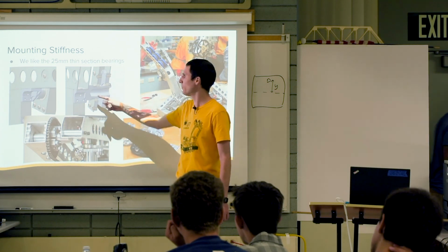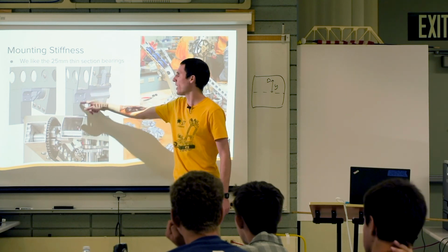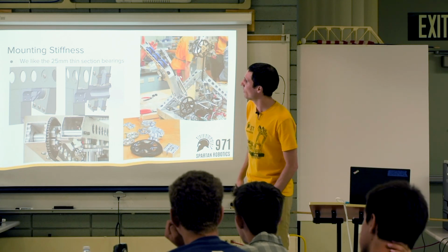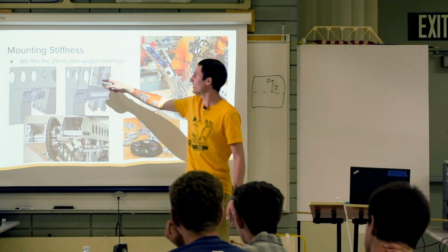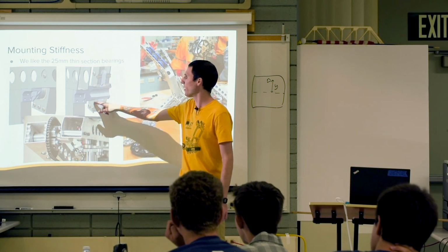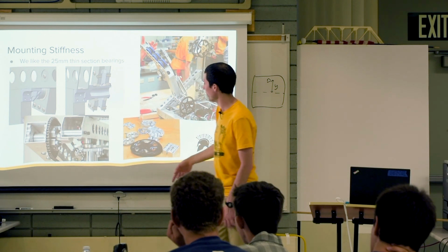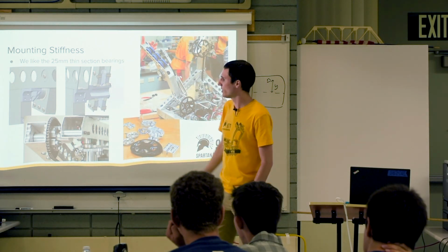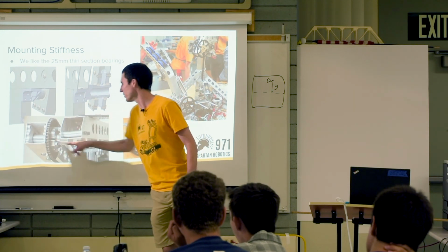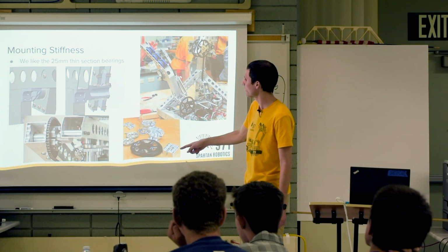This one was kind of nice. We milled it out of one piece, so we were able to bolt this straight on and have an axle there. And then the other thing we end up doing is putting the bearings inside of the tube. We just make these blocks that have the bearing pressed into them, and we bolt them onto the inside. We'll use that all over the place. And then here's another example of how we made an axle for something that was just a single piece.